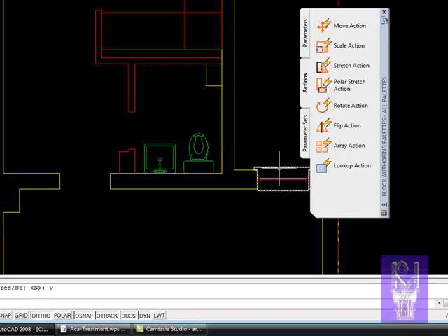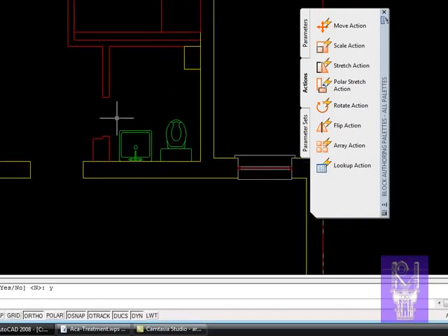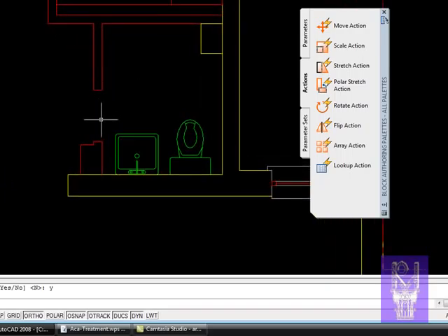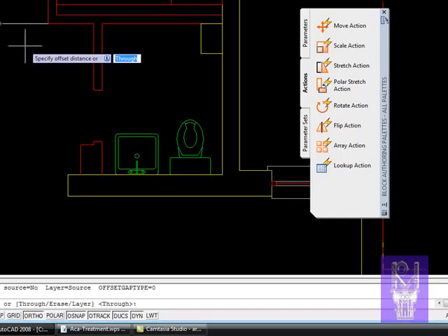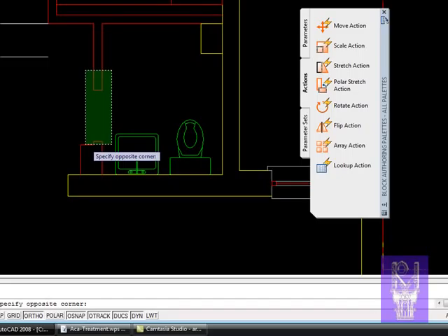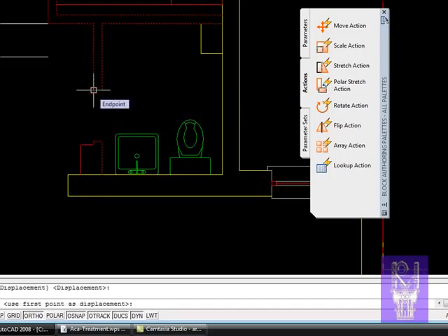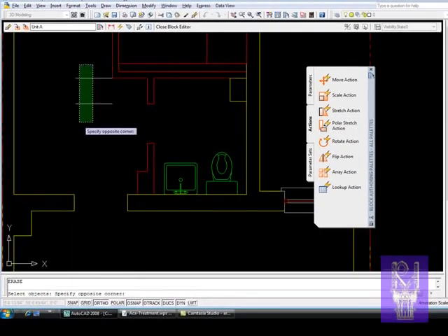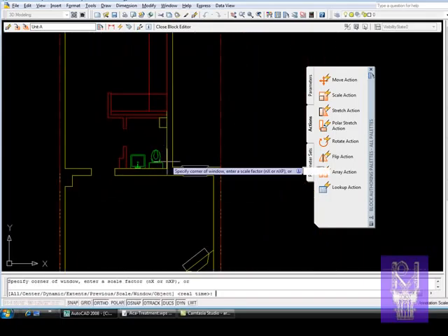and now it's done like that. But now what we need to do is stretch this condition up here. This distance here is 1 foot 3.5. So we can draw a line here at offset, enter, 1 foot 3.5, offset down. Okay, now we know that this whole condition goes from here, shift right click, perpendicular to this line, and then we're done. And then zoom extents.